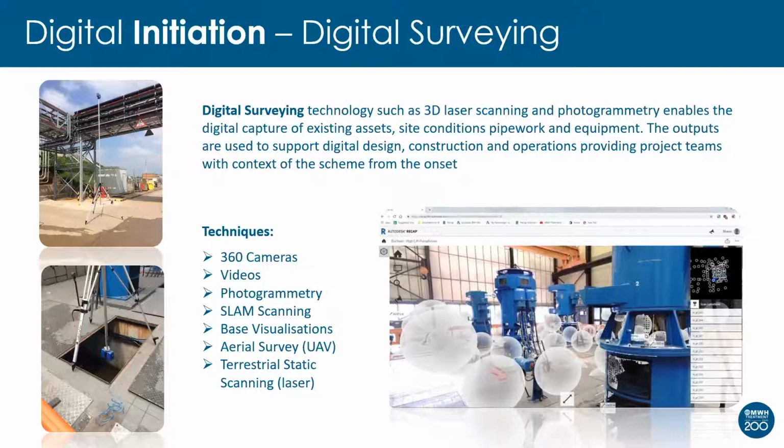Now we wouldn't take that many scans if we were just trying to get an appreciation of an area, of a field, of a car park. But where we're doing detailed engineering integration and it needs to be millimeter perfect, we go to this level of scanning. So the benefit of laser scanning is that it produces an output called a point cloud file. And as I say, if you scan to the correct level of accuracy, it's millimeter perfect to take forward into your design and base all your designs on.